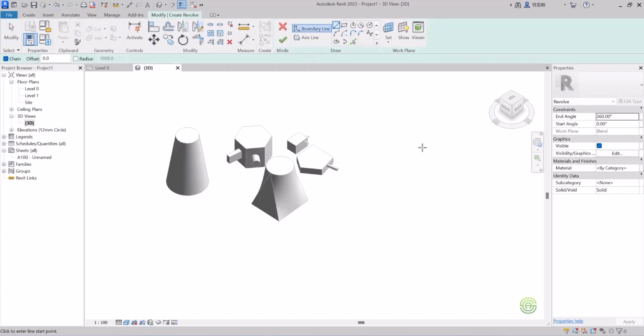I'll show you one. See, like this, you will have an axis. Around this axis, you will have a profile like this. So this is the main axis. In revolve, we have two things. First thing we have is the axis as a main thing. And around that axis, we will have one profile or shape, any kind. And that particular profile will just rotate around that axis in 360 degrees. It will create a circular form.